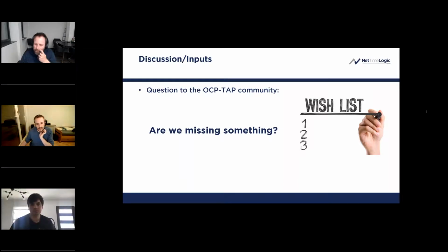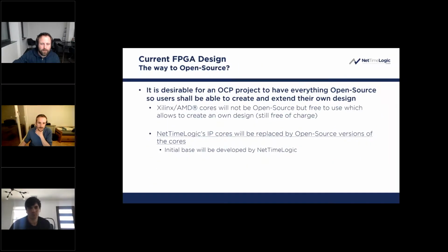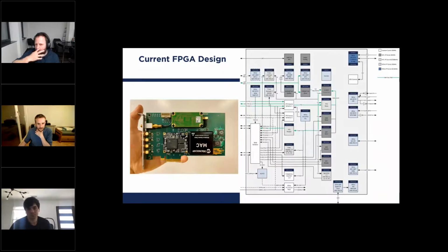So maybe you can quickly go to slide 6. There it's a bit visualized that we have already several bus masters in the system, so this is definitely no issue. On the top you can see UART to AXI, which has an AXI master, a static configuration which has an AXI4 master, and then we have the Xilinx bridge, which is an AXI4 master. So there are already several parts accessing this AXI interface.